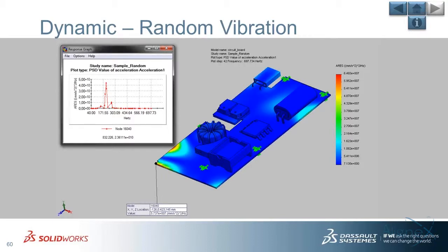And then simply apply that to our model. Again, the same types of things apply where we need to set up our fixtures and our contacts between the structures. If you want more information on that, I would suggest you do a little searching on response spectrum analysis. And I have seen in a lot fewer cases, sometimes random vibration analysis will be what people use with earthquake analysis as well.